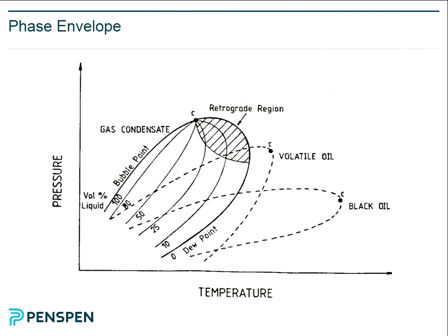So one way of transporting a product which would normally be multi-phase flow is to increase the pressure, and we call this dense phase operation. There are a number of pipelines around the world that operate like this. The disadvantage is you have a very thick wall because you're operating at something like 170 bar, 200 bar up here. But the thing is, at ambient temperature you've got no liquids basically.